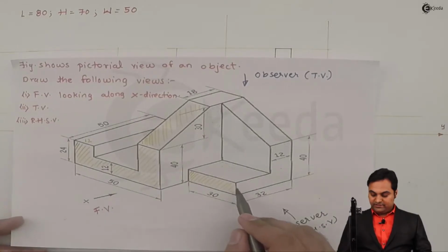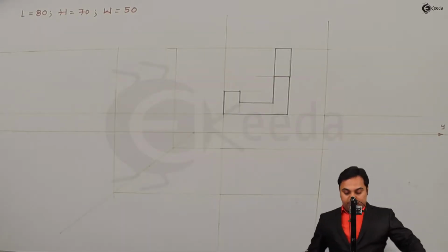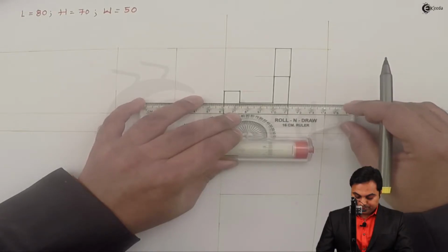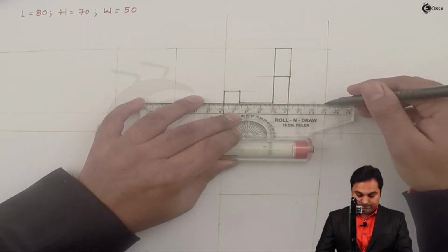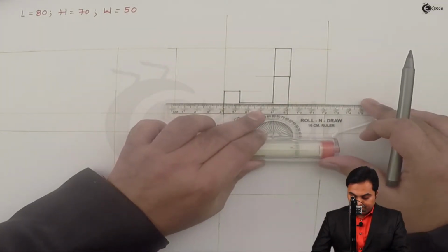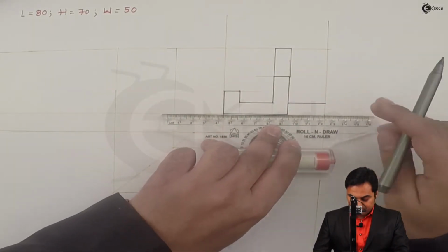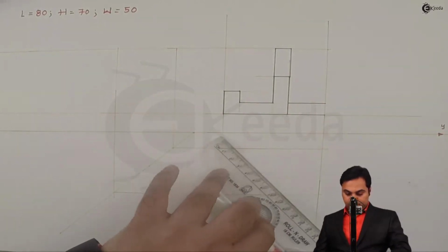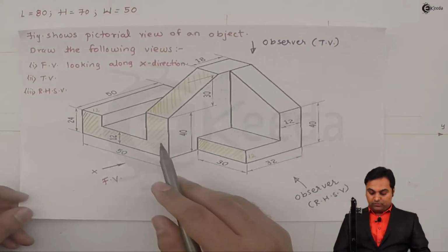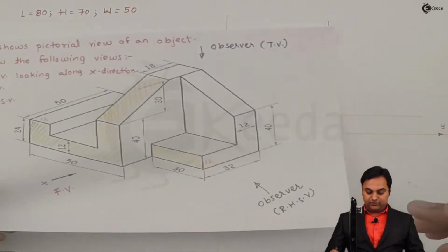And again it is also having the same height, that is of 12, as it is the complete surface going on. So I'll mark 12 mm height, projecting it directly from here. Now this rectangle will also be visible from the front, so I'm making it dark. Now as both these surfaces are on different planes, separating them is a dark line that indicates change of plane.